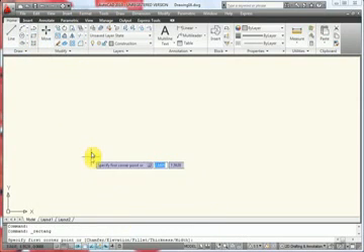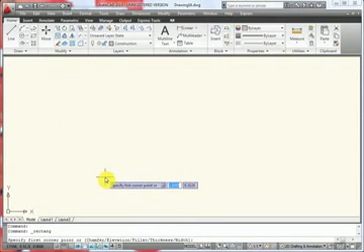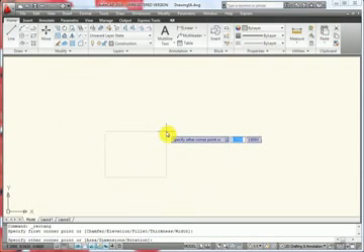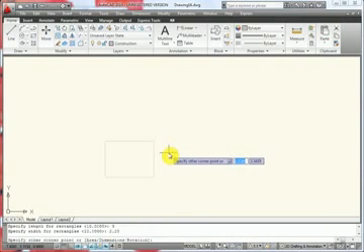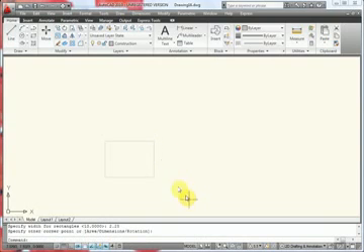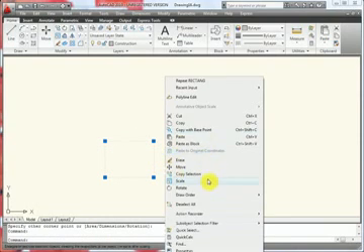We're going to make a construction rectangle. We're going to start off at an arbitrary location, and we're going to give it dimensions. So we'll put a D on the keyboard and start off with a 3 spacebar, 2.25 spacebar. Then I'm going to left click to place the rectangle. Now we want to copy a rectangle that is shifted up 0.75. So I'm going to select this rectangle. I'm going to right click in the graphics area and choose copy selection.